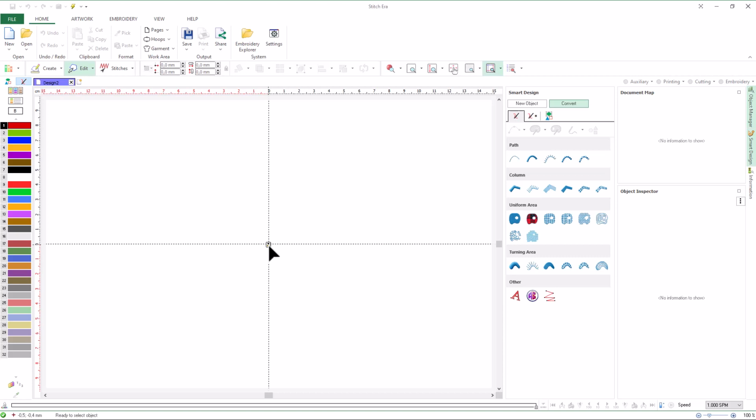In vector images, the contours of shapes are already defined in the objects that make up the image. When we create our embroidery objects from a vector image, we use those same contours, without the need to digitize them. In pixel-based images or raster images, there are no contours, but only regions of different colors. To create our embroidery objects, we need to digitize those regions. We can do it manually, visually following their edges, or we can use auto trace to recognize the contours of the regions in an automated way.